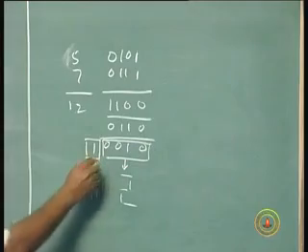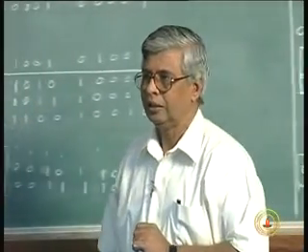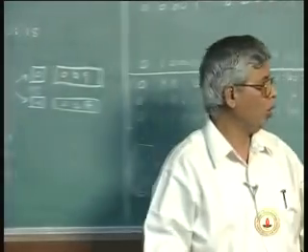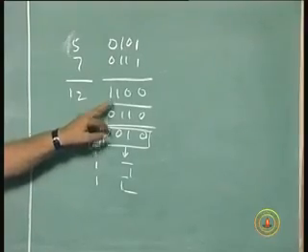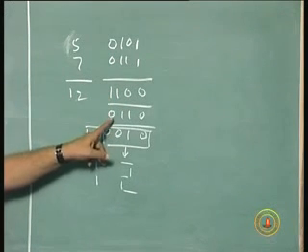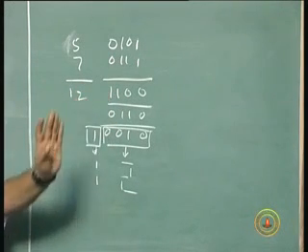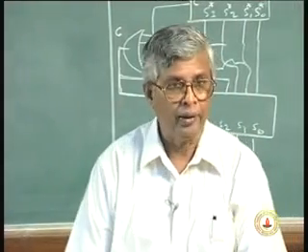That is why you are able to see 12 in your calculator, not 1, 1, 0, 0. This is exactly the point. So I should add 6 because this is more than 9. 10 and above I need to add 6. That's what I did. Okay.